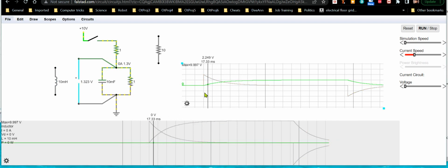The important thing to remember is that when the capacitor is at 0, you apply a voltage across it. That's when its current's going to be max, but the voltage across the capacitor will be slowly increasing as that current falls. But then when it goes into discharge phase, something similar but a little different happens. You get an initial negative current spike, and as that current falls off towards 0, your voltage also falls off to 0.